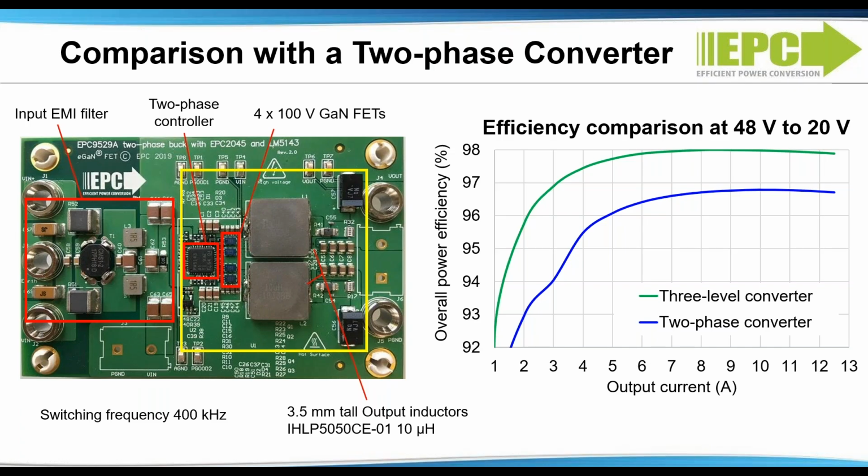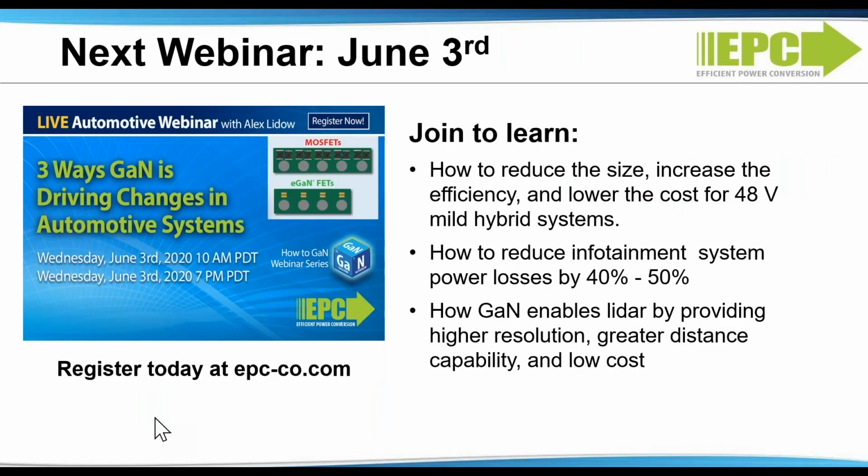How's the failure rate of GaN? Do you have a FIT value or PPM number in automotive? We have an extensive number of FIT values for different conditions and acceleration factors if you look at our Phase 11 reliability report.